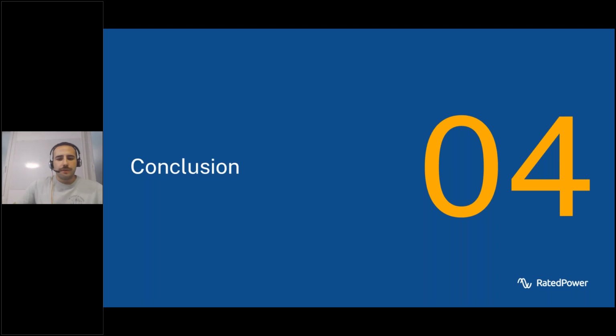Okay, let's conclude. So as we saw, it's really interesting doing this analysis and taking into consideration the land cost, because if we don't consider that land cost, we'll see that in terms of LCOE, the best design will always be the one with the highest pitch distance, and this is not a realistic case, as when we keep increasing the pitch distance, we will have that fixed cost that we have to consider.